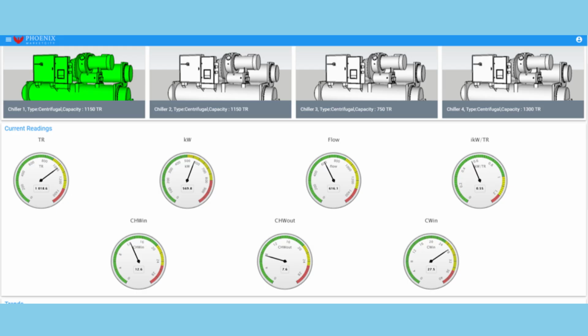Performance monitoring and ASHRAE Guideline 22. After commissioning, continuous monitoring keeps plants efficient. ASHRAE Guideline 22 outlines minimum instrumentation to track plant performance. Recommended daily metrics include outdoor dry bulb and wet bulb temperature, chilled water supply and return temperature, ton-hours produced, power input to each subsystem, chillers, pumps, towers, and overall plant kW/ton efficiency.